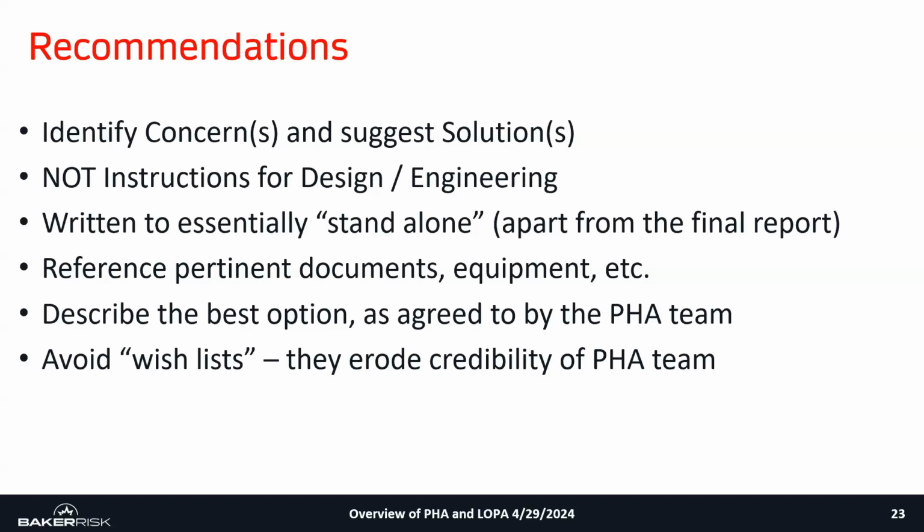And keep in mind that your recommendation should highlight a concern and provide a suggested solution. Recommendations are not instructions for your design or engineering team. The recommendation should be written in such a manner that anyone reading it, meaning just the recommendation alone, should understand what is being suggested and why. It's important to reference any kind of pertinent documents or information that would help the person receiving that PHA recommendation to implement.